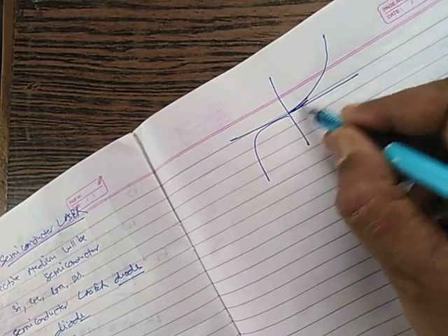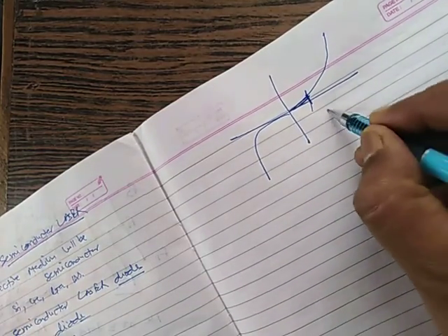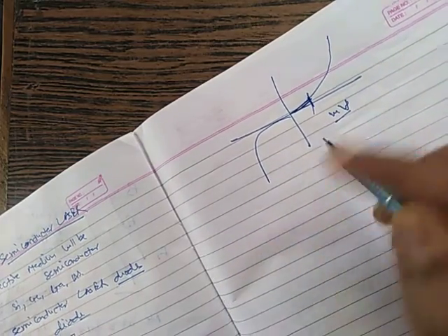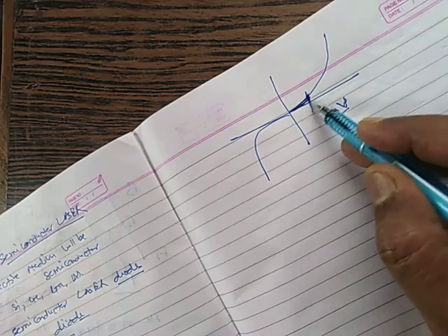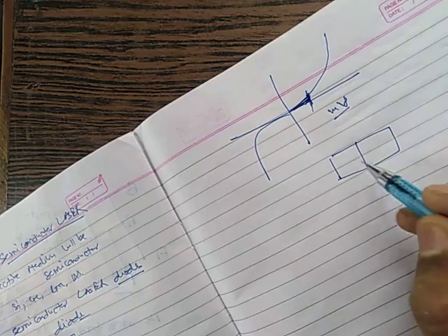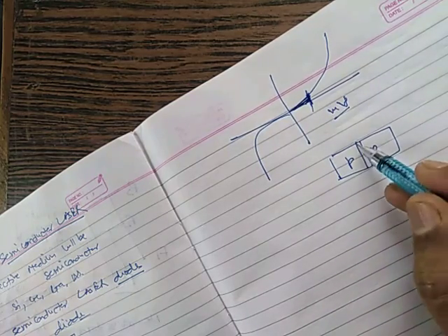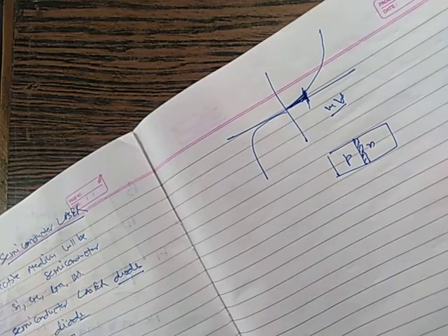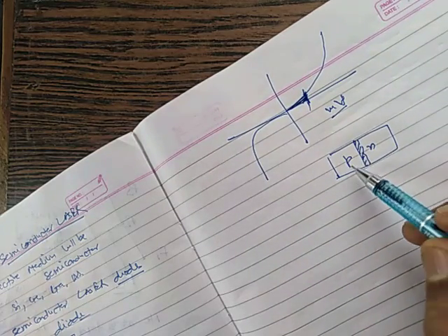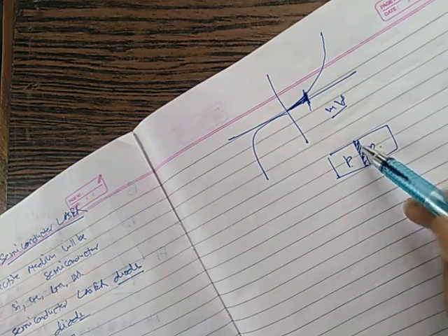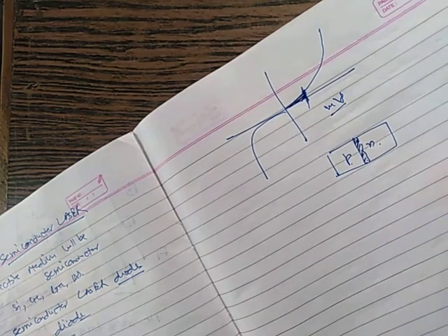Up to a few volts, a few millivolts we can say, the current is not there, and this is the voltage which is equal to the depletion region. As we know, when we connect a PN junction diode, a depletion region is formed where the charge carriers are not there, because the P type and the N type carriers neutralize each other, and an ion free region is produced, that is known as the depletion region.